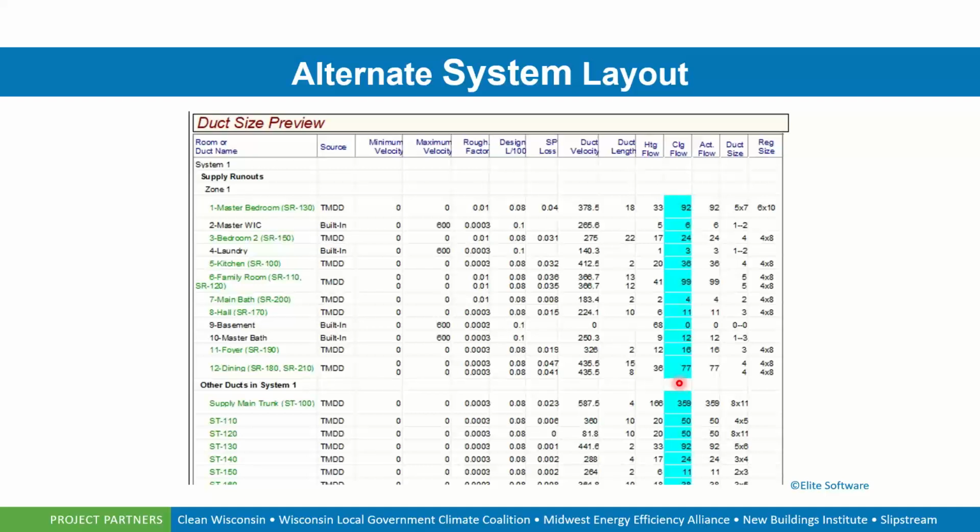So this is in a prominently cooling required environment, so this would be in the southern environment. We may have a different design of the same home in Madison than we would in Florida. Again, we need to make sure that we have the higher of these 2 flows. These are all tabulated and added up, and that gives us our total airflow within the home itself. We need to make sure that the duct system is designed to move that amount of air.